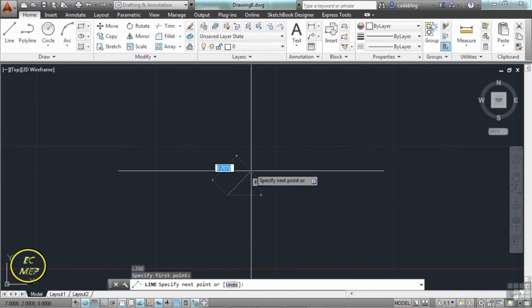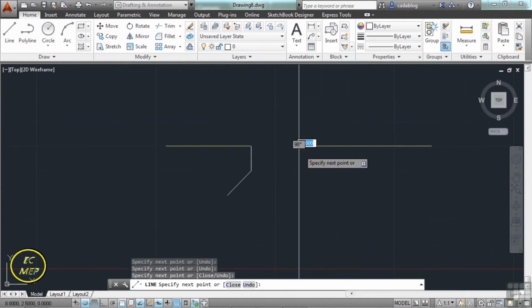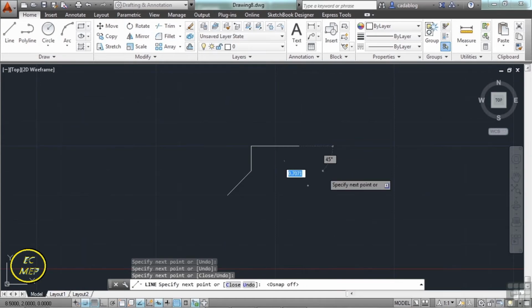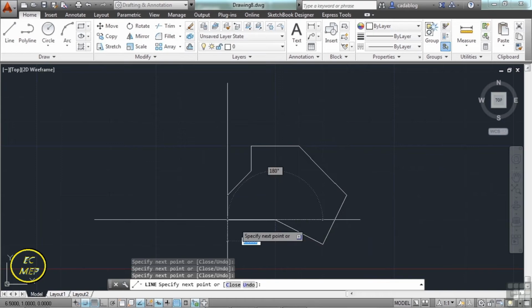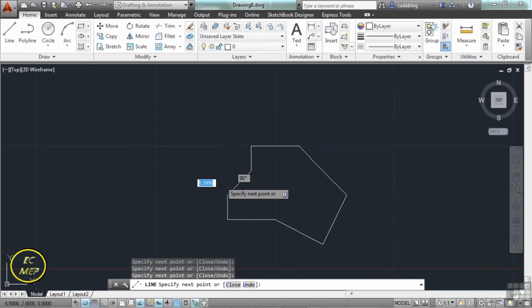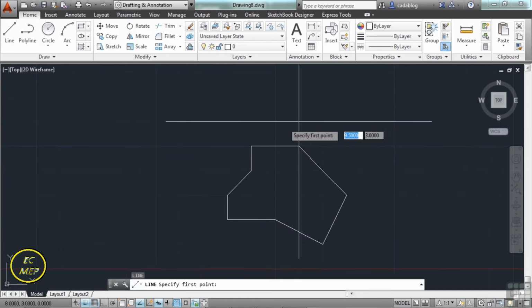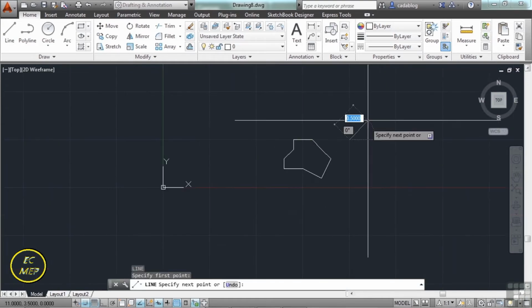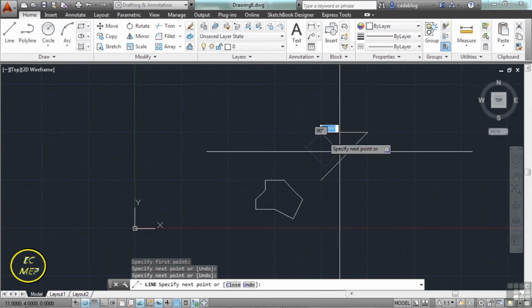With Snap On, as you can see, my cursor automatically snaps to lines on the grid. That's very useful. That's like drawing on graph paper. So I can draw from just about any point on this grid and know that I'm drawing accurately.